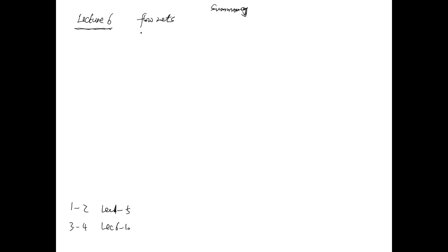So for lecture 6, firstly, you need to know how to draw the flow lines. You have to follow the rules. You draw the flow lines, normally 3 or 4 flow lines. That's already enough. And then you draw the equipotential lines, which will be perpendicular to the flow lines, and they roughly form a square, roughly everywhere.